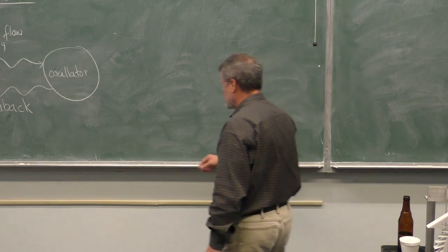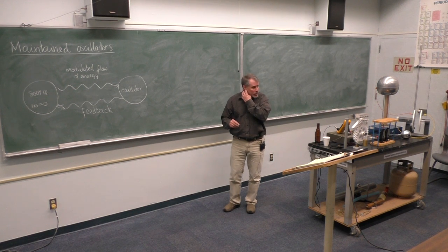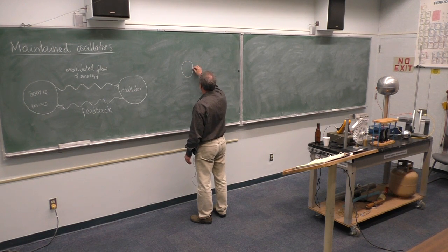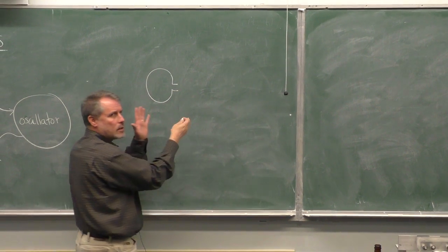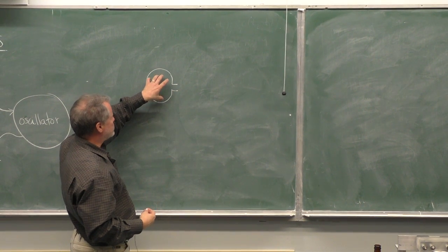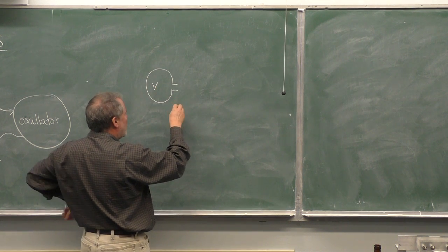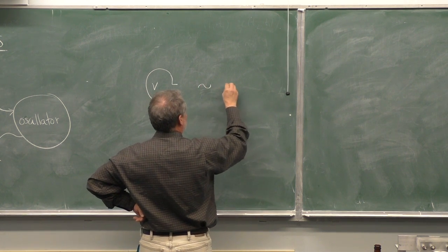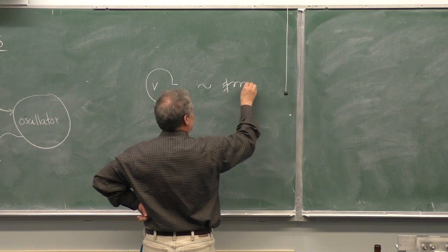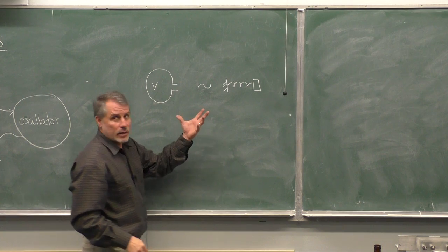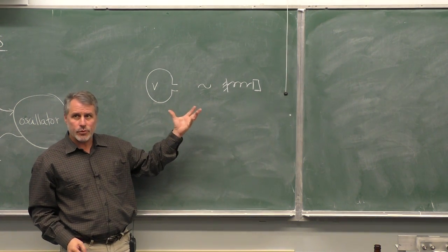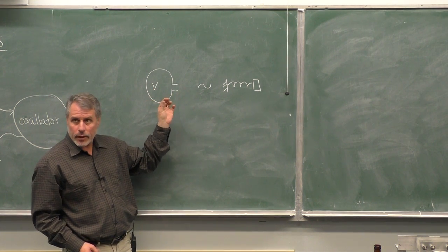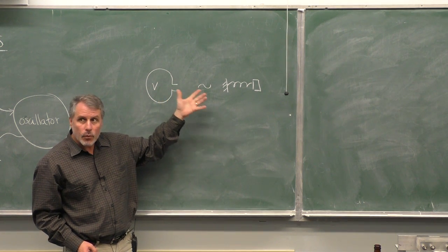We're going to see the Helmholtz resonator later as well, but just so we understand it, it's just a volume that has a neck, and you can change the neck, extend it, shorten it, whatever. You have a volume V, and this system mechanically is equivalent to a mass and a spring. So there is only one resonant frequency to the Helmholtz resonator. Given the volume of the resonator and the particular neck, we would have only one resonant frequency.